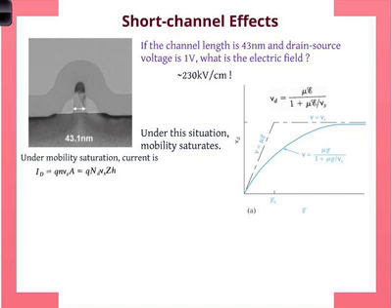Okay. These are contacts, so metal. So it is P+, but you don't need to worry too much about it. You have a PN junction here, right? That's your gate. Source, drain, and you have the same thing on this side. Plus, ignore everything else. I'm simplifying it quite a bit. Now, when you apply a gate voltage, you are building a depletion region, right? Now think about that equation and see what does the gate voltage control.